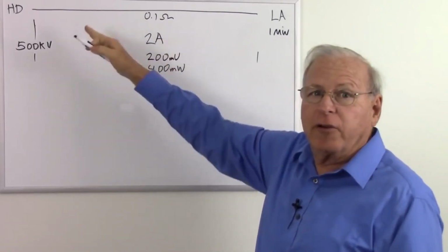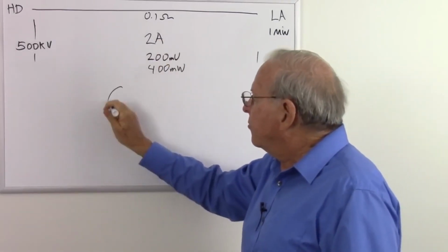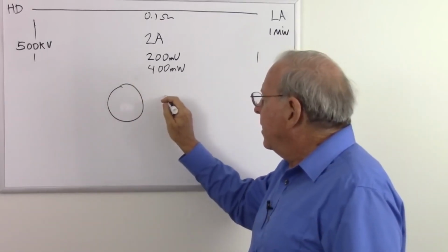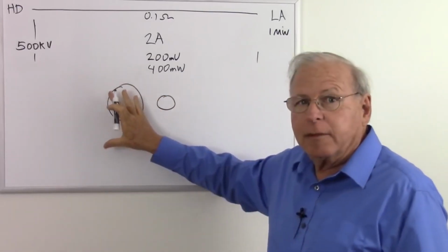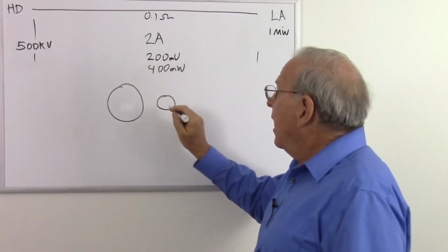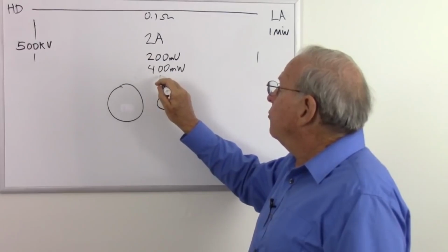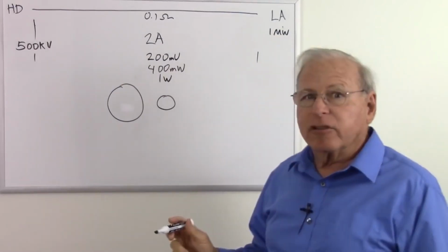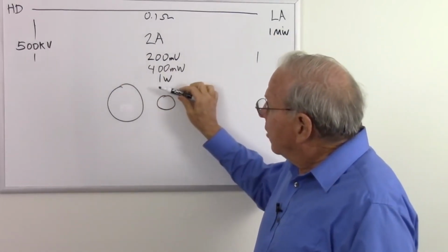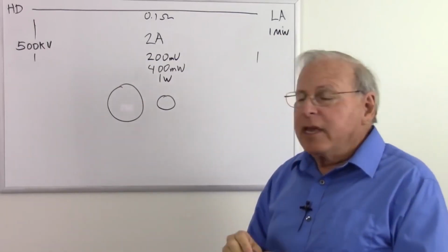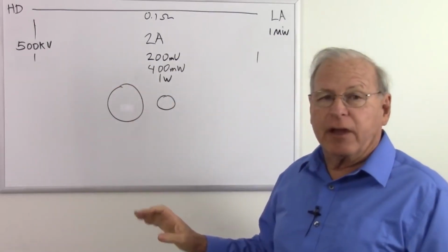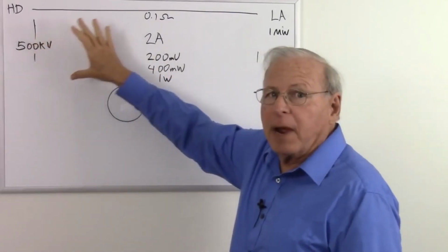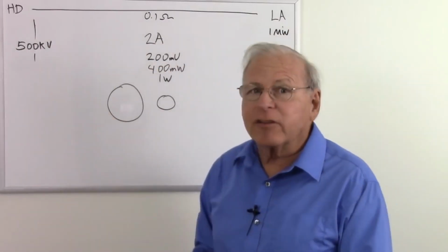And in fact now, since we're carrying so much less current, we can take that 70 millimeter wire and reduce its size. Let's just cut the diameter in half and make that 35 millimeters. So we're actually cutting the bulk of the wire by 3/4. And doing that, we're still only going to use 1 watt delivering that power all the way to Los Angeles. And in fact, we reduce our losses so much that instead of using very expensive and rare copper, we can use steel reinforced aluminum to deliver our power and save a lot of money in the process.